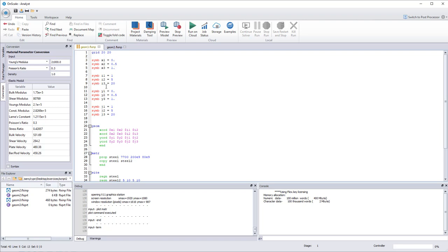So what I did is that I basically said, okay, I want a grid with coordinates 0, 0.5, and 1. So I'll just call those coordinates x1, x2, x3, and then the nodes which are associated to those, I'll call those nodes i1, i2, and i3. And then I do the same for y and j nodes. So you see that I always have a pair of coordinates and nodes. I have two kinds of coordinate system, the XYZ coordinate system and the IJK coordinate system. So here I have no Z and K because I'm in 2 dimensions, but in 3D you'll have K and Z as well.